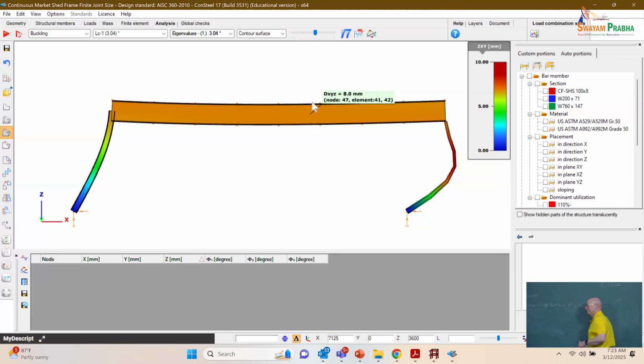What happened? We added continuity, the buckling load went down. Or at least the buckling mode involving side sway went down. We had a lower buckling mode on the HSS section before. So is this side sway buckling, or is it non-sway buckling? Or is it neither?